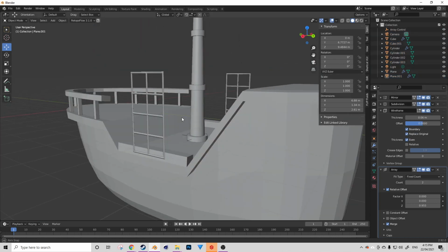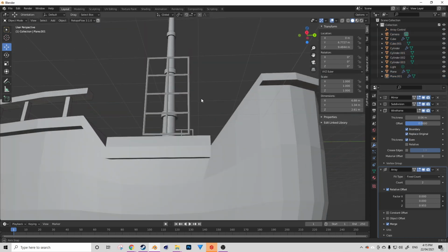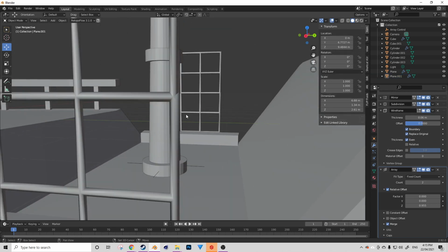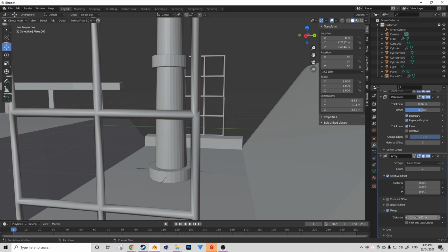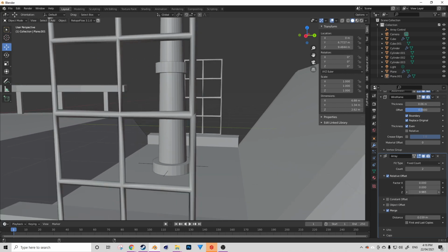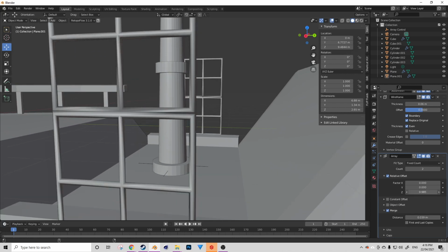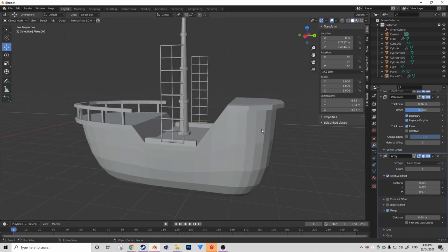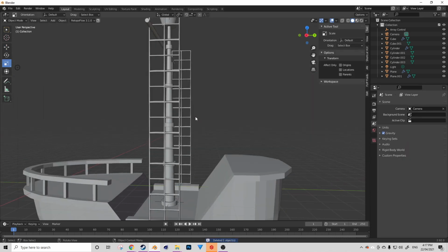One way we can tell that this is all merged together nicely is we can set the shading to be smooth. Now, as you can see, there's a little bit of problems in that area there, so we can play around with the distance of that merge. Now, as you can see, it's not really helping too much. So let's play around with the Z transformation on the array, and you can see what's exactly happening here. Once everything's nice and smooth like it is here, we know that everything is merged together nicely. So we can just increase the array now, and it's going to keep those merges intact.